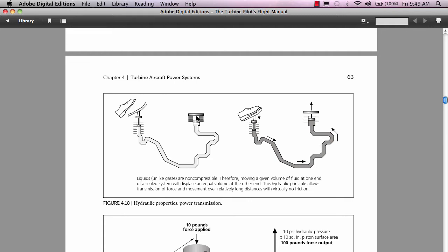And as you can see here, let's talk a little bit about the mechanical advantage. You have a small cylinder that goes quite a ways, and then you have a larger area slave cylinder, and this may have to move 10 inches at 10 pounds, where this will move 1 inch at 100 pounds. So your foot can generate, we won't call it mechanical advantage, we'll call it hydraulic advantage, to produce a large force at this end with a small application. But again, you have to move this cylinder quite a bit farther to produce some movement on this larger surface here. Just like I talked to you about the car jack. With one hand you can jack up a 3,000 pound car, but you have to put in lots of movement on the jack handle to get it to come up.